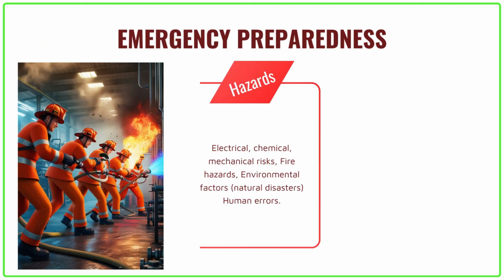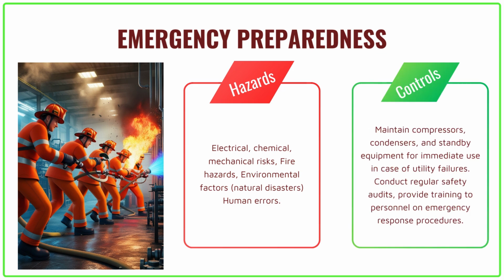Emergency preparedness. In emergency preparedness, hazards can arise from utility failures and environmental factors such as natural disasters. Maintain compressors, condensers, and standby equipment for immediate use during emergencies. Conduct regular safety audits and provide comprehensive training to personnel on emergency response procedures.